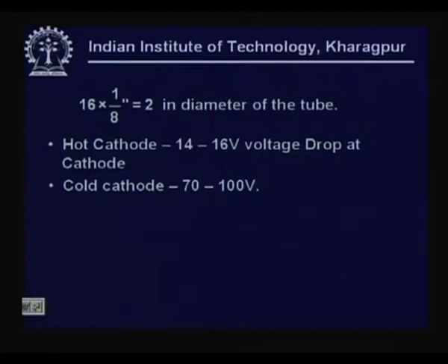We did mention in the earlier lectures also that there would be a requirement of a higher voltage source in order to have electric field assisted emission, and that is not desirable. Therefore, the understanding of incandescence becomes even more important. We have similar filaments at either end which are heated by the passage of current and thereby produce the discharge.